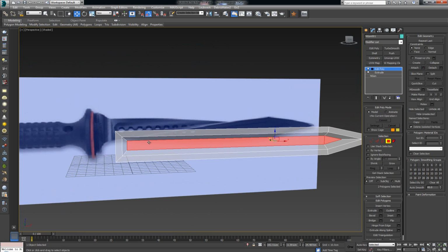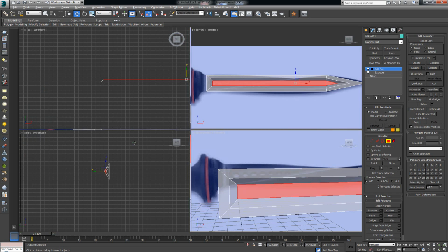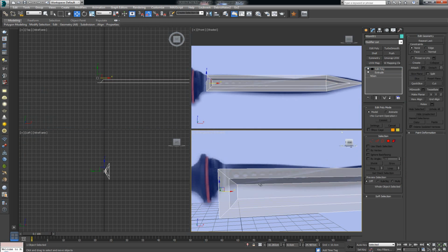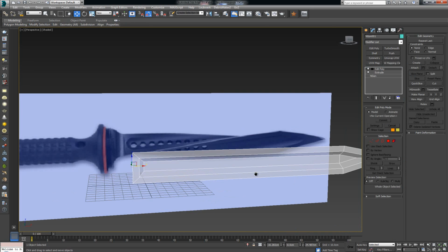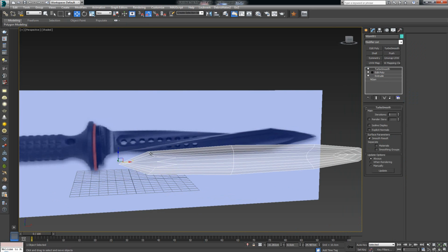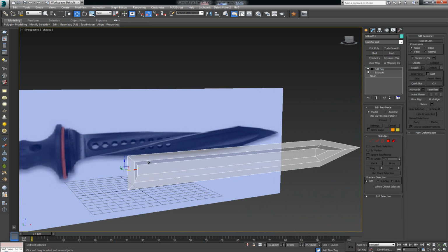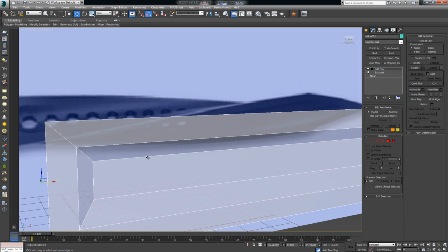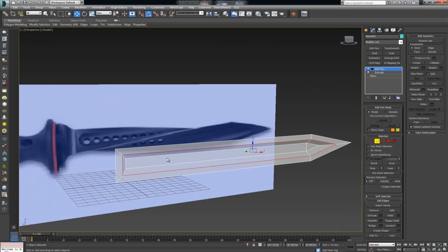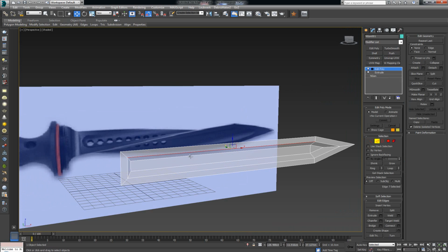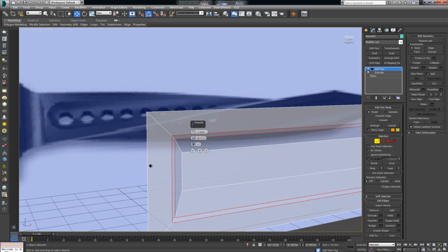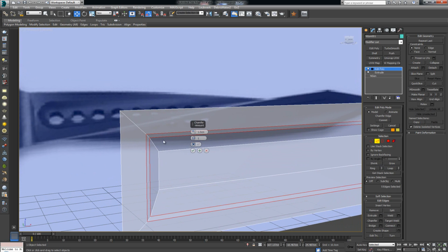All right. Now, if I leave it off like this and I apply a turbo smooth, I'm going to get this portion just breaking all up, which is not what we want. Instead, we want to hold this edge. So I'm going to select my entire loop. Just press one of these edges, go loop, and now I'm going to chamfer it so I get a bit more geometry to hold this edge.